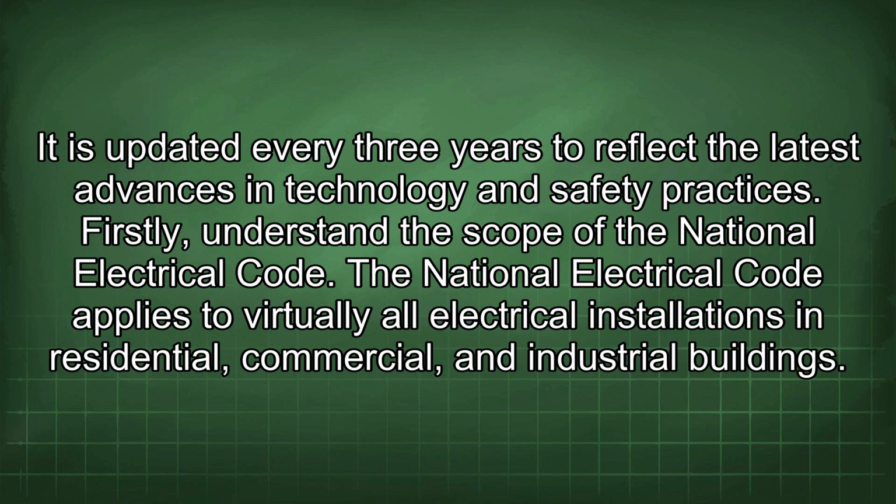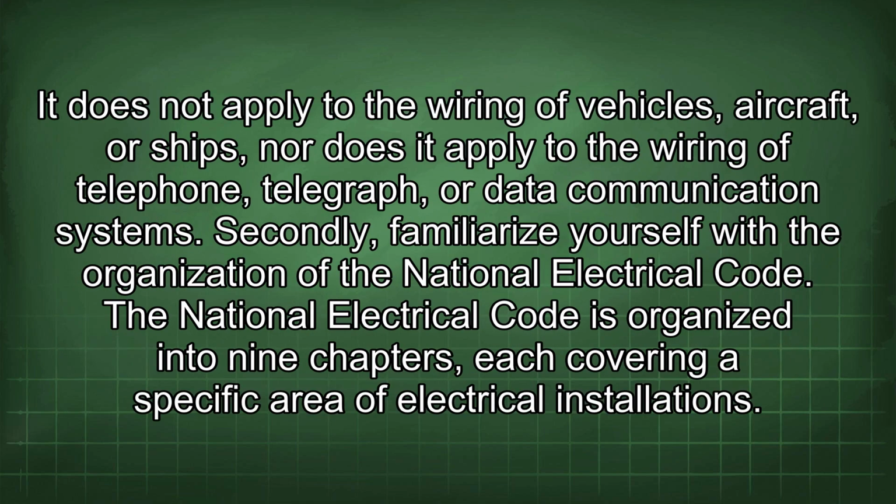Firstly, understand the scope of the National Electrical Code. The National Electrical Code applies to virtually all electrical installations in residential, commercial, and industrial buildings. It does not apply to the wiring of vehicles, aircraft, or ships, nor does it apply to the wiring of telephone, telegraph, or data communication systems.